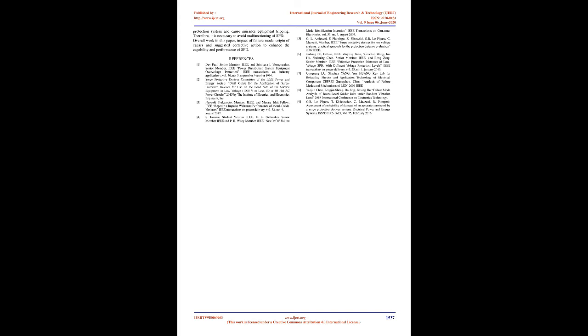2. Poor quality components. This includes bad soldering and cold joints, poor connectivity between circuit boards, insufficient board thickness, and use of counterfeit components. The effect on material is bending and breaking. To mitigate it, use the proper thickness of board as per rating and the required solder paste aid. 3. Environmental factors. This includes dust, moisture, power overload and surges, and premature circuit board failure due to electrostatic discharge, which exerts thermal stress on the PCB. The remedy for this problem is cleaning and maintenance of the PCB and proper neutral grounding.